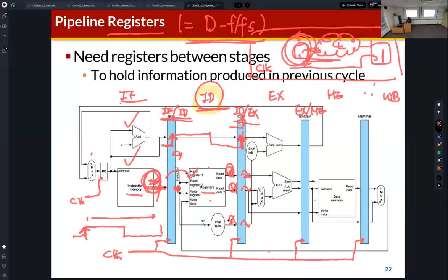So we can understand the pipeline architecture like this. Between stages, we just insert pipeline registers, or groups of flip-flops, and signals are sampled at the rising edge of the clock. Then the sampled data is delivered to the next stage.